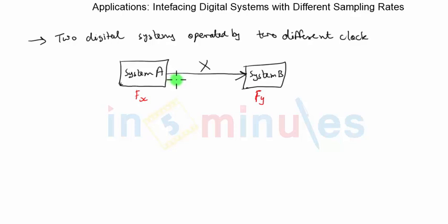of system A. The analog solution to this problem would be to convert the signal from the first system to analog form and then resample it at the input to the second system using the clock of the second system. This is something we had discussed in the beginning also. This was the first approach to carry out sampling rate conversion. However, a simpler approach is one where the interfacing is done by a digital method using basic sample rate conversion methods that we have already described.